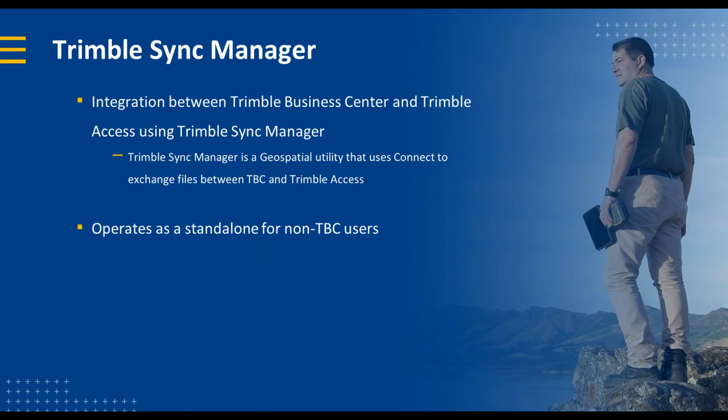For those that aren't using TBC, you can run Sync Manager standalone. So you can drop files in there, it creates your jobs and sends them out to the field. So the one big difference with Sync Manager over Access Sync in the past is Access Sync was just syncing files. Once that file turned up on your device, you still needed to go and create a job and link that file. What Sync Manager does now is you drop the CSV file or the RXL and all that sort of stuff into Sync Manager, it actually creates that job for you based on the properties of TBC. So everything's all set up and it comes through to the data collector and the job's created and it's all ready to go. So it's a lot quicker and a lot simpler.